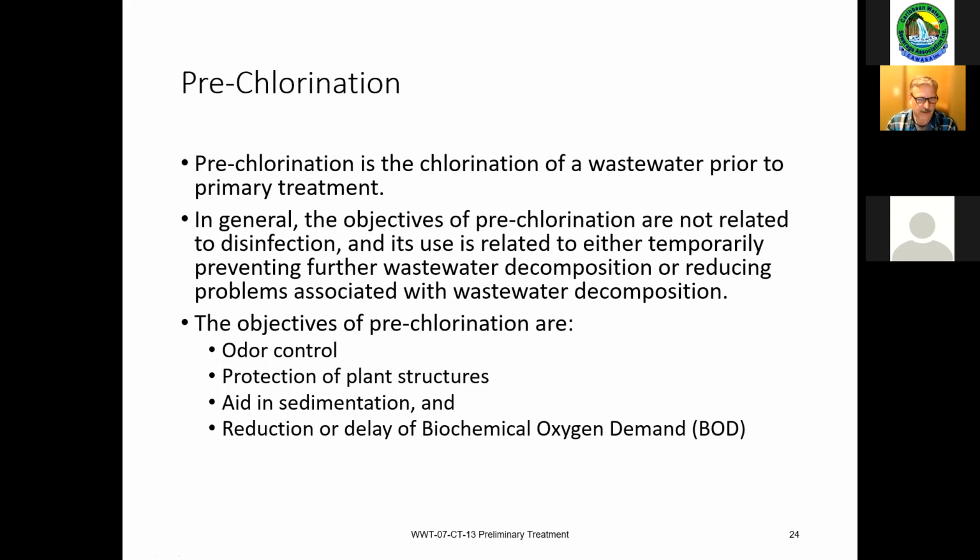There are a lot of other chemicals out there now that are used for odor control as opposed to chlorination or pre-chlorination. The biggest concern with pre-chlorination is chlorinating too much, or over-chlorination. With over-chlorination, you'd kill anything that's alive in that waste stream. Typically you would then have a carryover of that chlorine into your biological reactor, which is then going to turn around and kill the microorganisms that are in there.